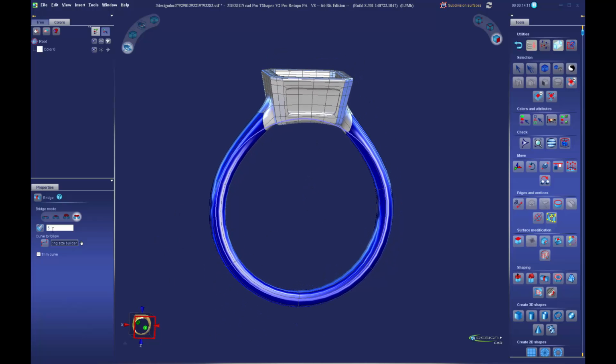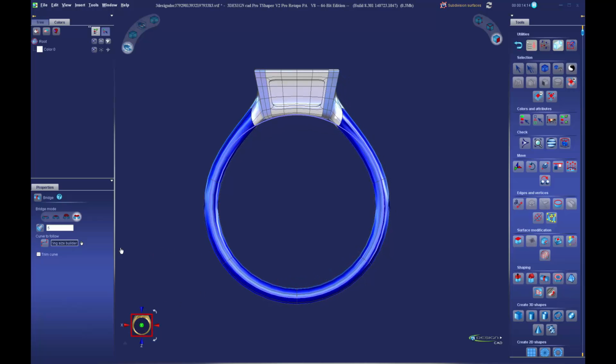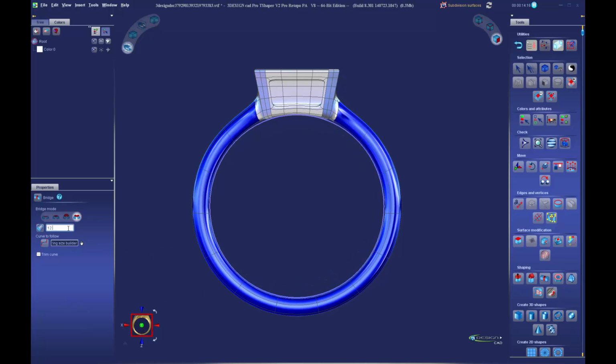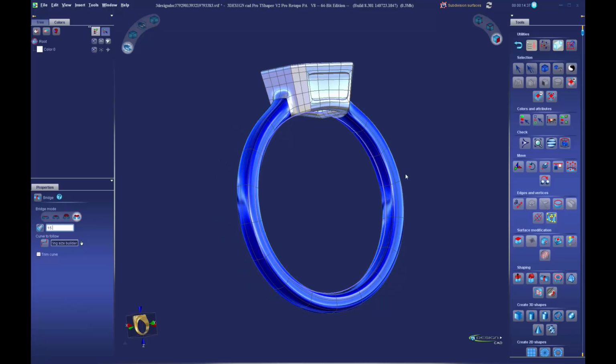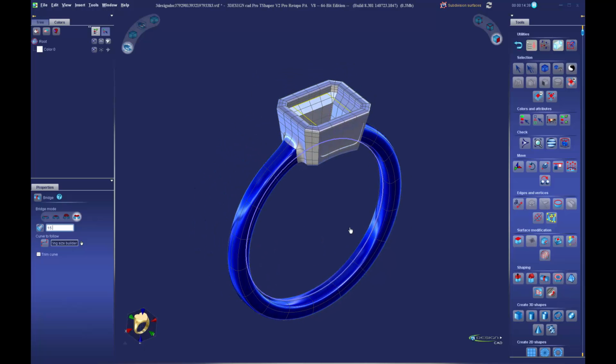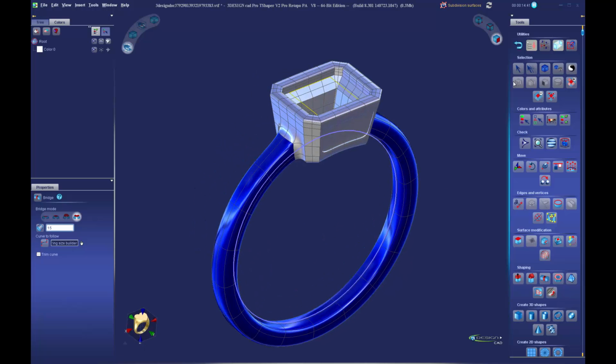So it's only 5 subdivisions by default. We may want to raise that number to about 15. I like to do a nice odd number. That gives me an edge right at the center in case at some point I want to split this ring in half. I have that edge already in the middle. So that should be plenty. 7 splits on either side plus the 15th right in the middle. And that'll match our finger size. So that'll give us our shank.